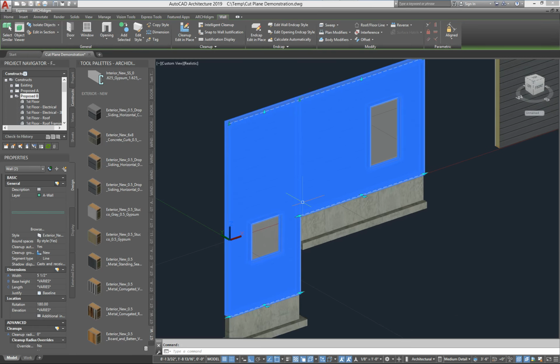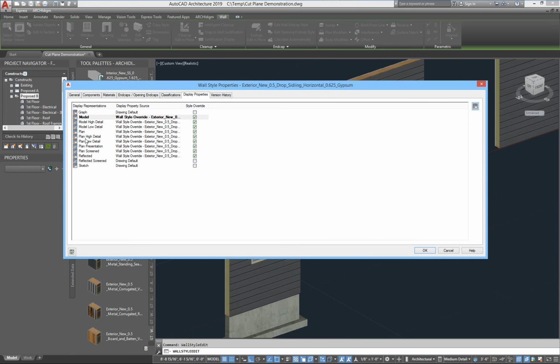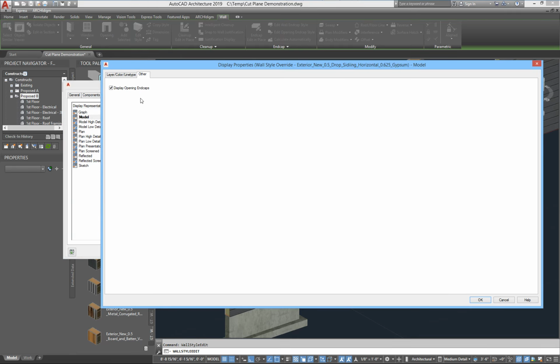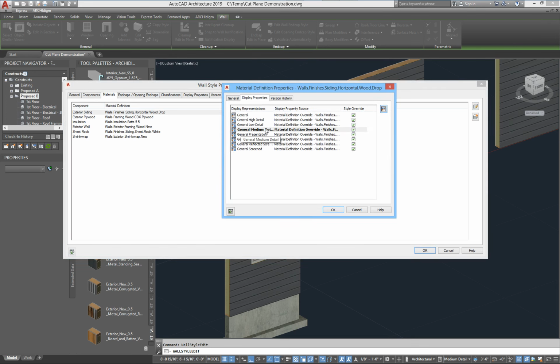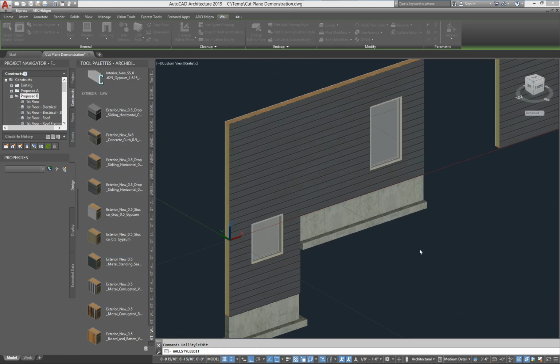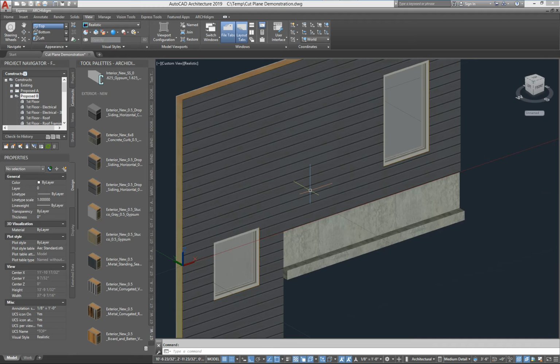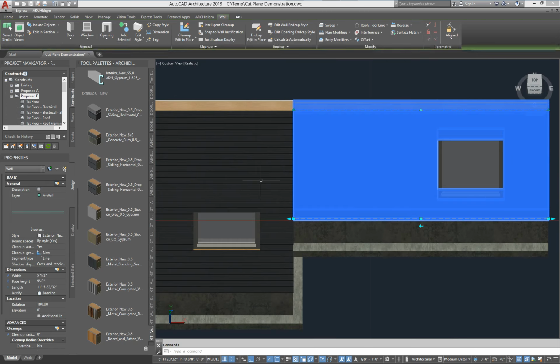And then for more advanced users, what you do to keep that line out between those two things when you're doing your projected elevations is you use the merge common material setting. I'll just quickly show you that. When you do elevations or sections, it uses the model, and you go to materials. This is the exterior siding. You go to the properties of the materials, general, medium, detail, other, and then you'll see right here where it has merge common material. That will prevent a line, usually, pretty good, maybe 80% of the time. It will not show a line where those two walls come together like that.